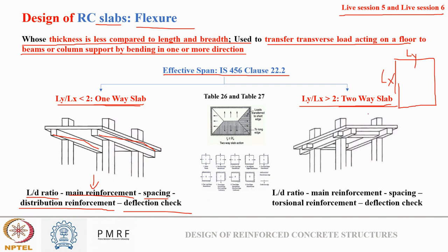Okay. Now, when we talk about two-way slabs, these slabs are those which can span along both directions, and thus supports are needed along all four sides. So in this, we first saw how load distribution is done. For a one-way slab, load distribution is simple, half on one side and half on the other side. But when my slab is spans along both directions, my load distribution diagram appears like this. Okay, and for this load distribution diagram we saw different cases also, whether my edge is continuous or not continuous, and how I take the factors alpha x, alpha y, beta x, and beta y based on the dimensions of the